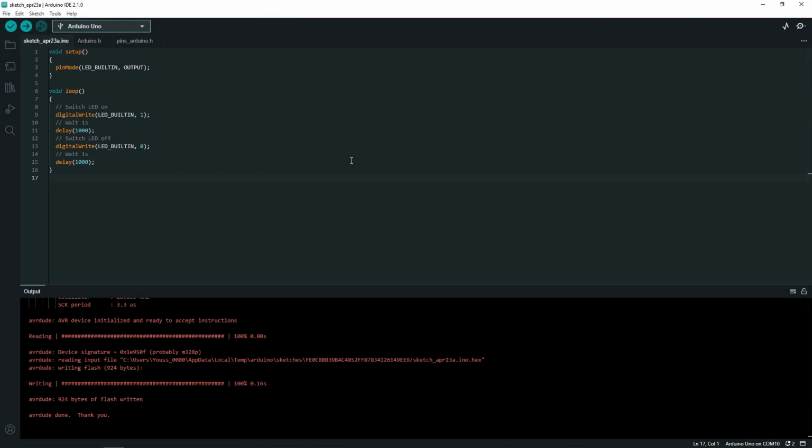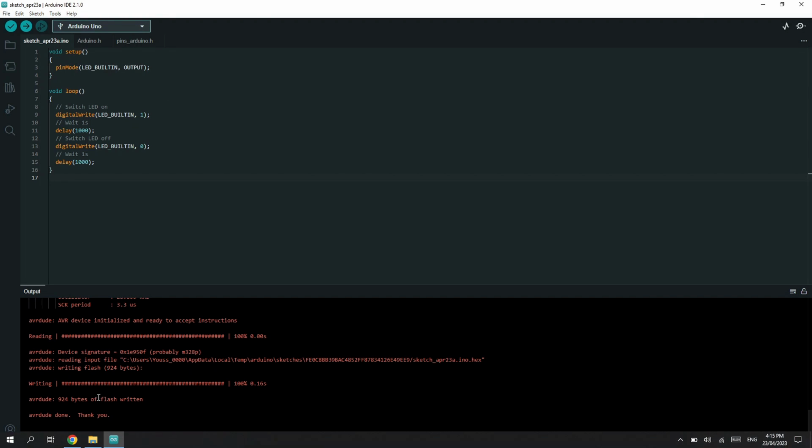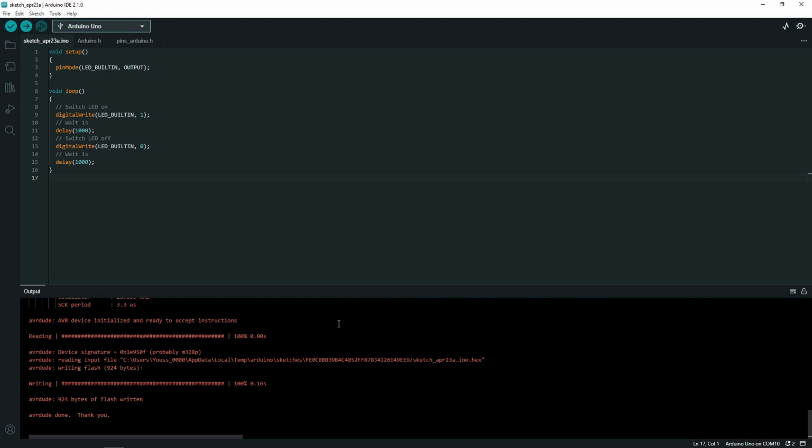So now moving on to the serial monitor. What the serial monitor is, is a way for you to be able to print things to a console on your screen while your Arduino code is running, to be able to tell when certain lines of code happen and if certain information has been sent over.